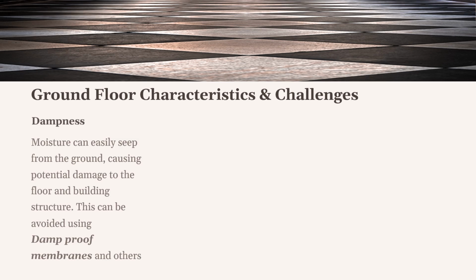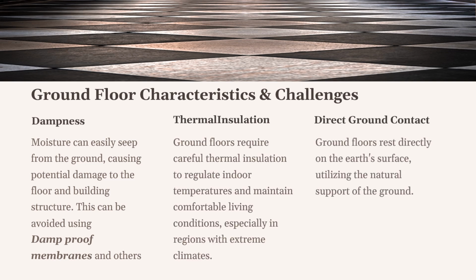But here's a catch: ground floors face challenges when it comes to dampness and thermal insulation. Moisture from the ground can seep into the building, leading to potential damage and discomfort. To combat this, builders use damp-proof membranes and other techniques to keep moisture out. Plus, ground floors need effective thermal insulation to maintain comfortable indoor temperature, especially in regions with extreme climate.